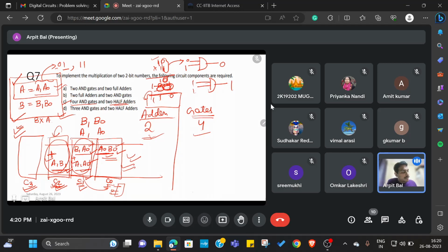In this case I took a generic example to demonstrate how these products are generated and how the carry propagates. And we observed why this generic representation is needed, because if you take any particular case, let's say if someone takes 0 0 0 0, then he or she may say that we don't need any adders at all because there won't be any carry, but that's not true. If you are making a 2-bit circuit, you need to ensure that it is functional for all the possible cases.